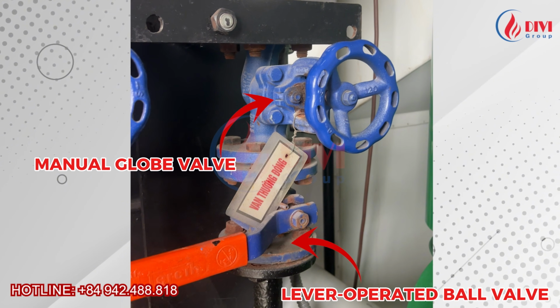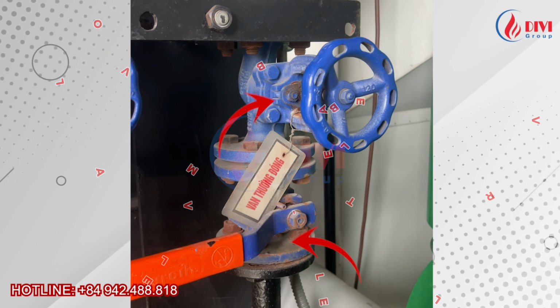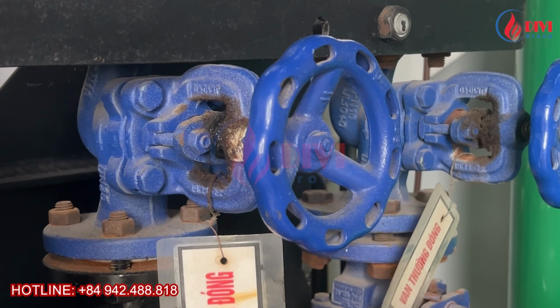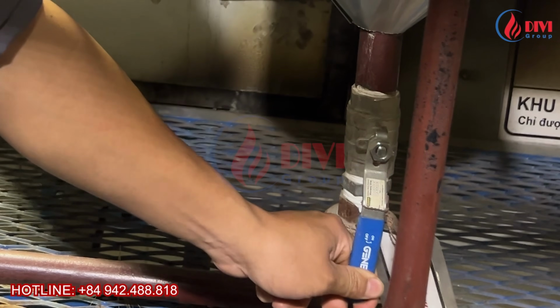For smaller blowdown points, only one valve, either globe or ball valve, is sufficient. According to the design, surface blowdown uses a globe valve for flow control, as it mainly removes soft impurities. Gauge glasses use ball valves for quick operation when checking water level signals.